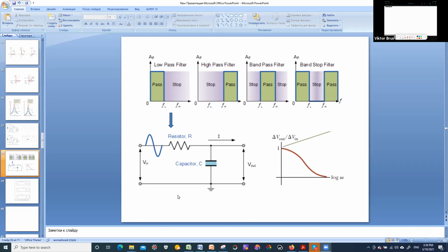However, if frequency increases, the resistance of resistor R is a constant parameter. It doesn't change with frequency. And we know from previous lectures that capacitive reactance, this opposition of a capacitor to AC electric current, decreases with increase of frequency.